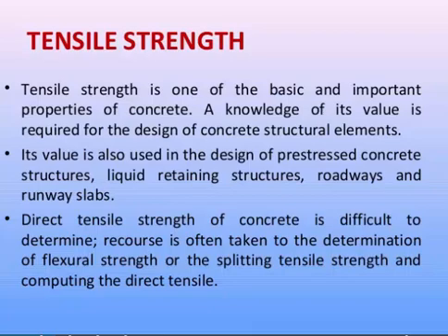Because concrete is very weak in tension due to its brittle nature. Hence, it is not expected to resist direct tension. Concrete develops cracks when tensile forces exceed its tensile strength. Therefore, it is necessary to determine the tensile strength of concrete to determine the load at which the concrete members may crack. So that is why it becomes an important property, right?